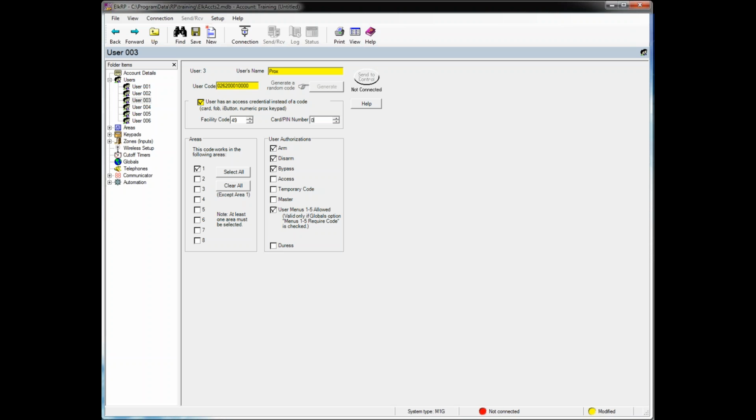And this is, again, information coming off of like one of the Elk Prox cards, and we'll just say that the number coming off of it is 55692. You'll see when I entered that information it automatically populated this user code field. This is going to be a user where I only want them to be able to unlock the doors in area 2, for example. You can see how, just checking boxes there, you can make those selections.